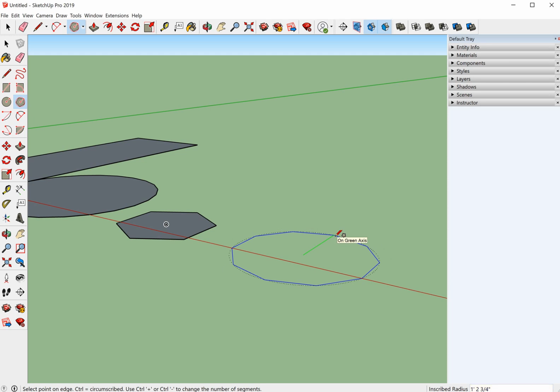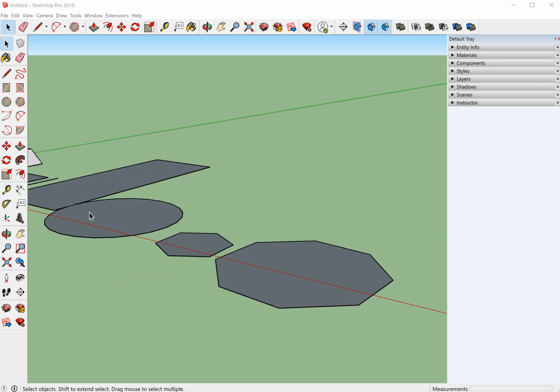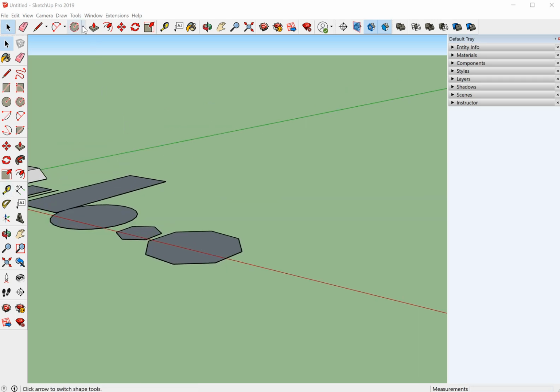You have to put the S behind the number because that indicates to the program that you're talking about sides. So then it'll give you the 8 sides, and then after that, you can specify the radius. Okay? So obviously the difference between the polygon and the circle is that with the polygon you can specify the amount of sides, and with the circle it's just a circle.